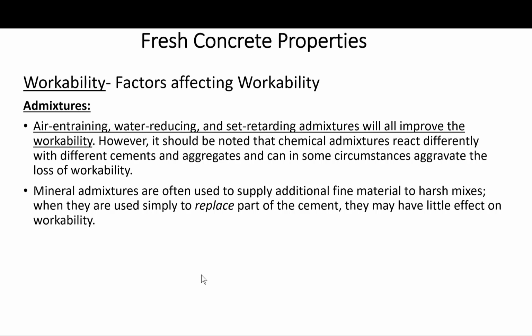Okay, also admixtures, definitely, as we have mostly looked at during the lectures on admixtures, both mineral and chemical admixtures. So chemical admixtures, like air entraining, water reducing, and or set retardant admixtures will all improve the workability.